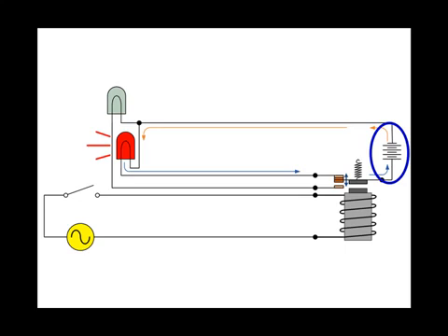The coil is wound around a pole piece of ferromagnetic material. As current flows through the coil, a magnetic field results, and this field is intensified by the pole piece that the coil is wound around. The resulting magnetic field from the pole piece magnetizes a piece of magnetic material that is attached to the moving contacts, the armature. As this piece of material becomes magnetized, the two magnets are attracted to each other. The spring yields to the magnetic force, and the two magnets are drawn together.